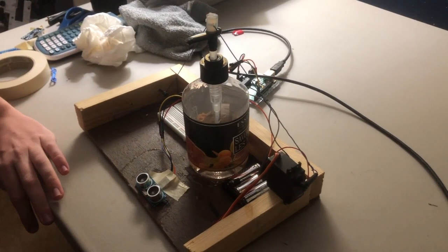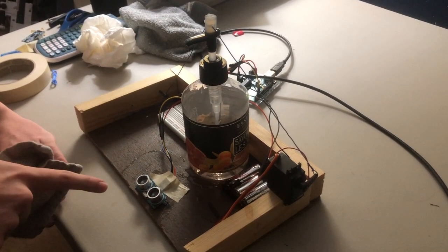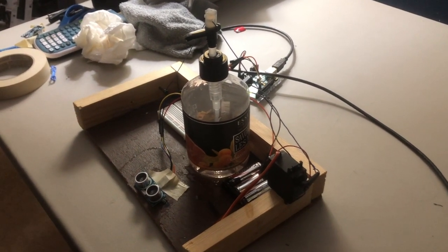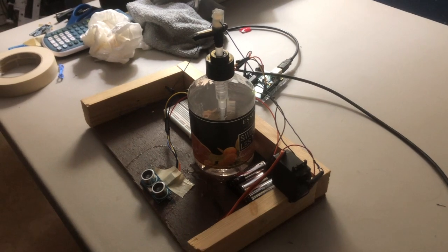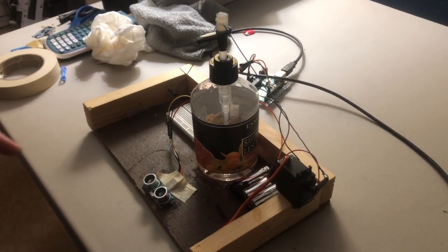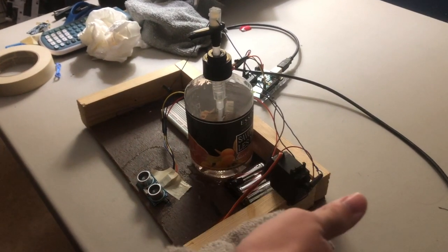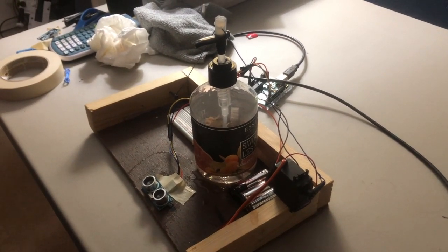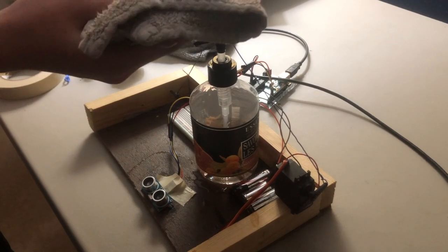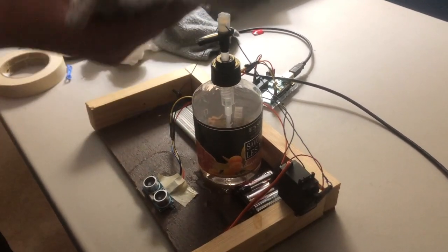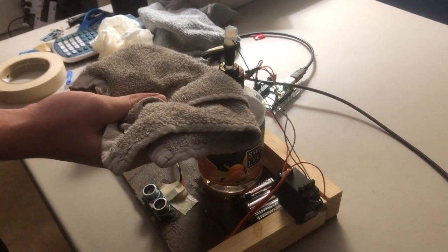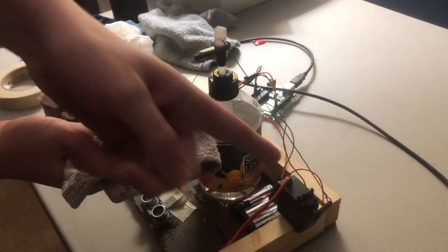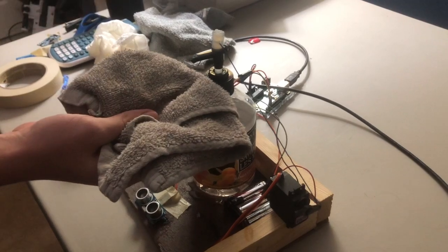Okay, so I put power to the Arduino, so now when I put my hand in front of the ultrasonic sensor, if it's below the height of the nozzle, so that's about 18 centimeters, if it's below that 18 centimeter limit, the ultrasonic sensor will tell the servo to rotate and depress the galvanized steel wire. So over here, nothing happens, but as I get just below that nozzle, we'll see that servo actuates, pumping the liquid.